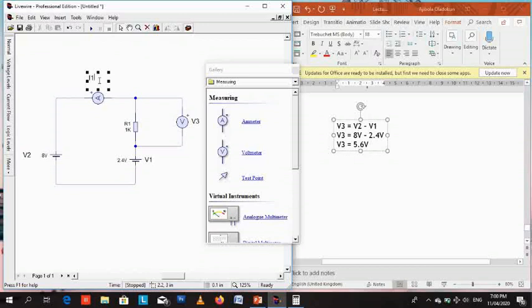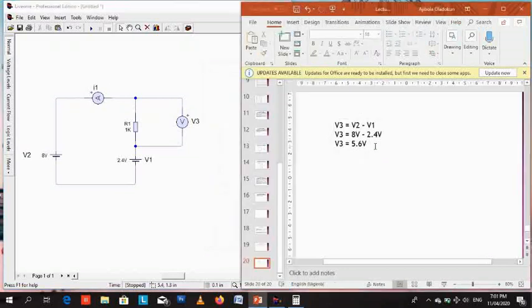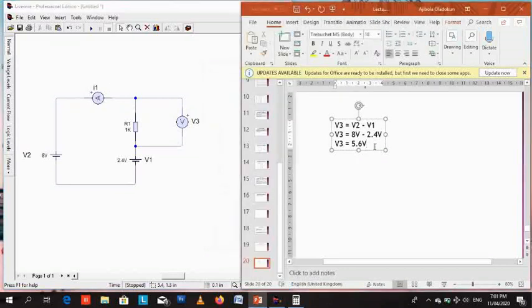So we see here that we got 5.6 volts across the resistor in the calculated value, and then the measured value was about 5.54 volts. So it means that there is a drop across the wire, the cable. Basically the cable is like a resistor on its own, but in the ideal case it should not be. The resistance should be basically zero. But in actual practice, there will be a little drop. So it won't exactly be 5.6 volts as you have in the ideal case. Measured in the real world, there will be a little drop.